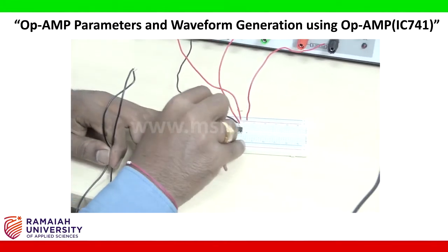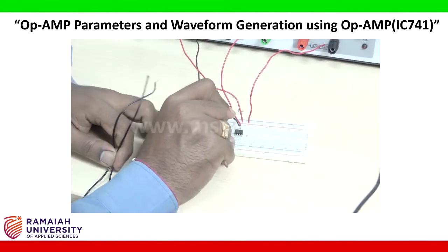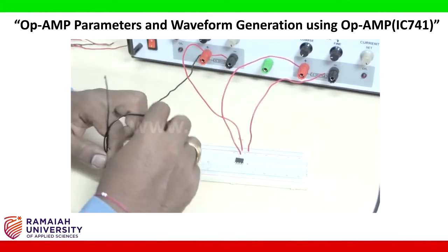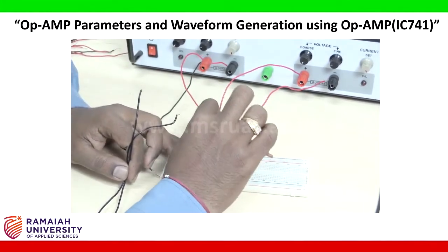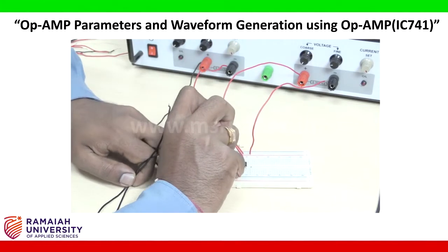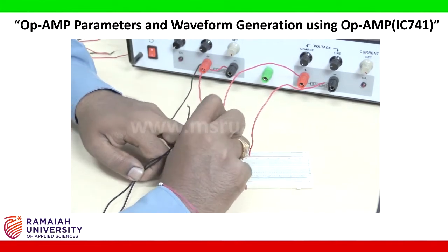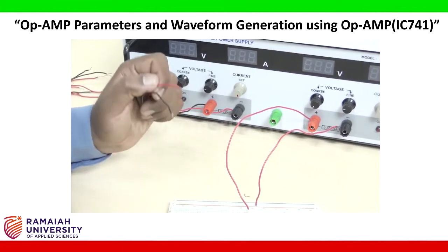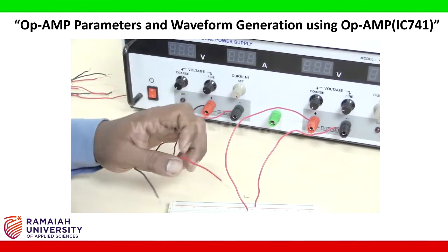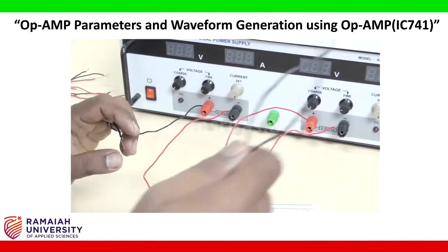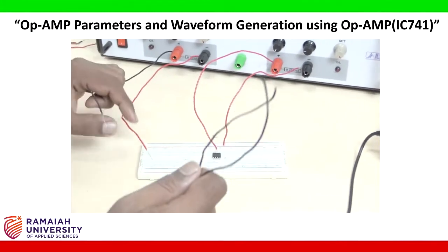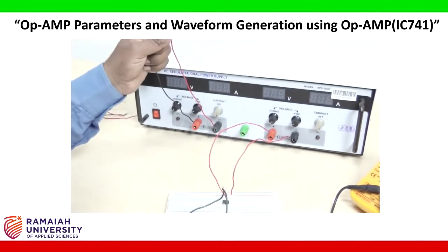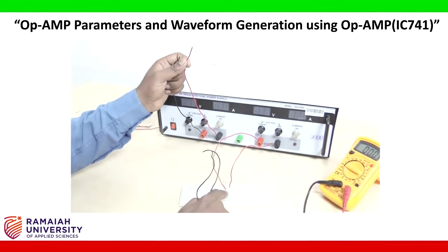I took one voltage positive terminal and removed the same voltage's negative terminal. I want to measure the current in terminal 1, so I want to make this multimeter in series connection with this voltage and this chip.